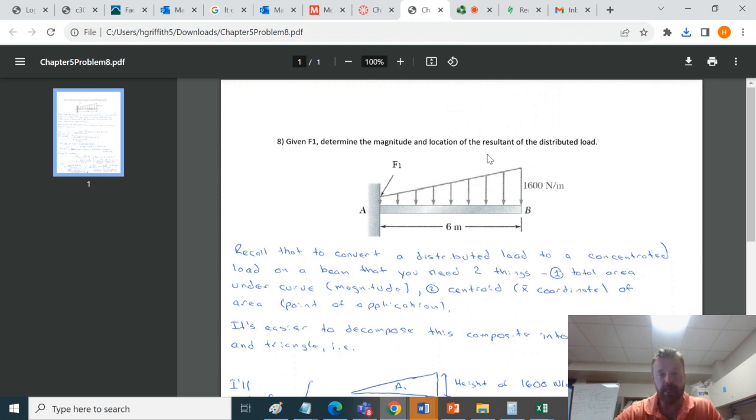It would be relatively simple because we've worked this kind of problem previously in the text. It's just that the beams in that case hadn't been subjected to a distributed load. It had just been single individual forces or concentrated loads. So we know how to do this problem overall if we can take the distributed load and represent it as a single concentrated load. So the question is, how do we do that?